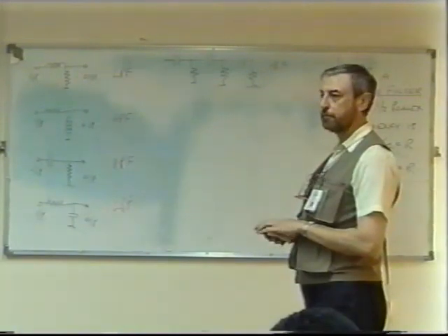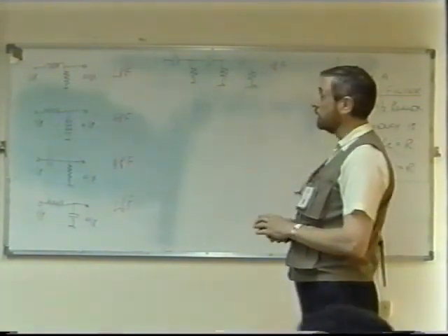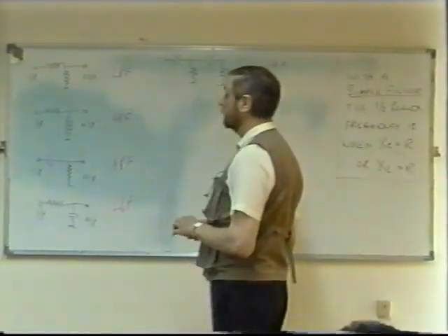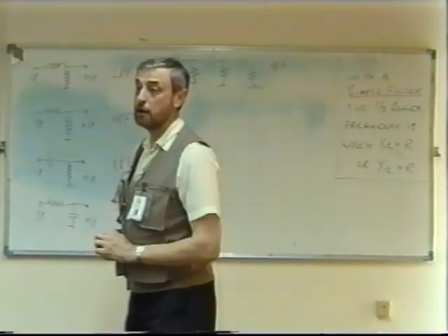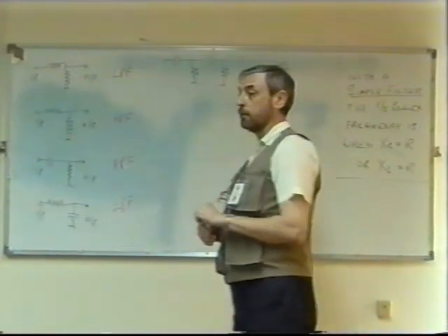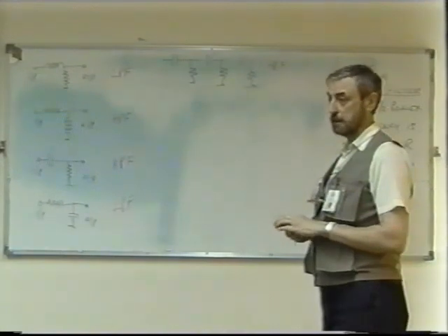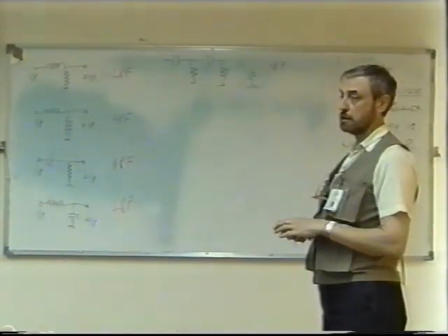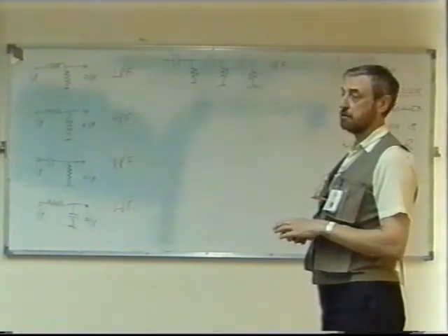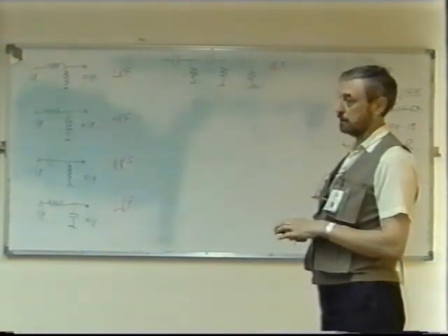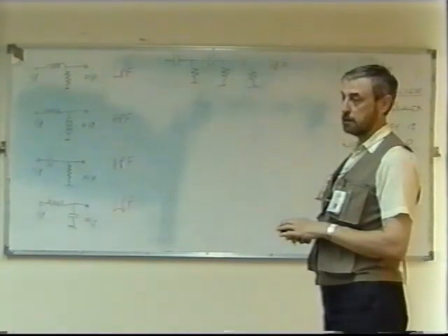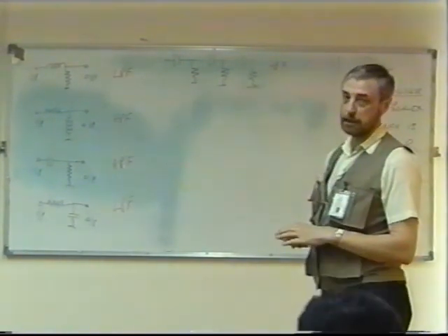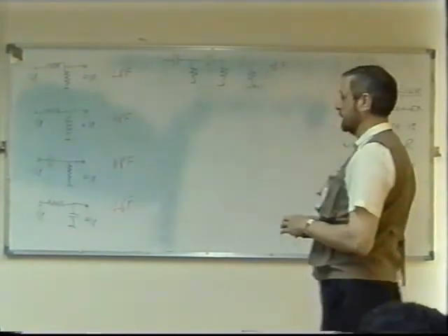But can we say it's cut off? You can still calculate it, although it's more complicated. You said it's a high pass filter. And the other thing that you gave us before, the cut-off frequency, is the same as the minus 3 dB and the half power frequency. They're all the same, also the same name. That doesn't make any difference on the type of filter. That's any type of filter.